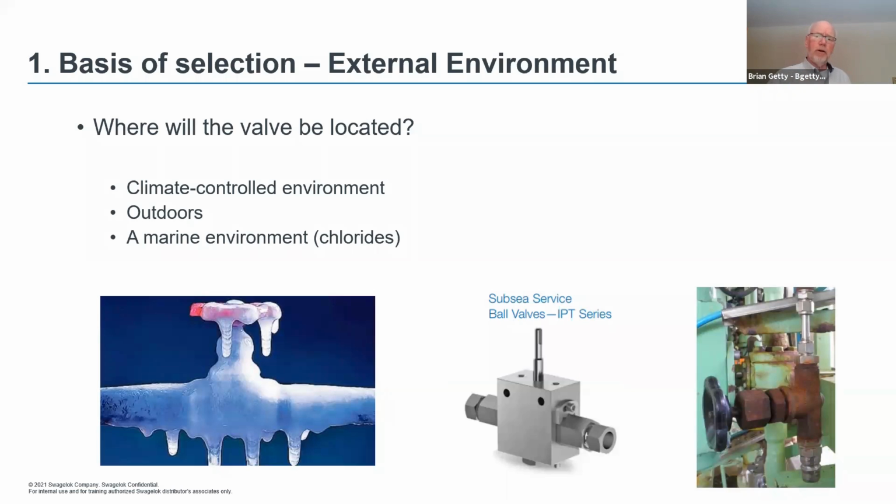Or in the second photo here, is it an application where it's a valve that's going to be installed under the sea? Of course, you get down 300, 400, 500 feet in the ocean, you're dealing with some severe pressures. Plus you've got the chlorides, the salt water, which will attack a valve from the exterior going to the interior. Extremely dangerous if you've got the wrong material under sea, and it could be on a gas line, a gas system. You want to make sure you've got the proper product. So your external environment is very important.